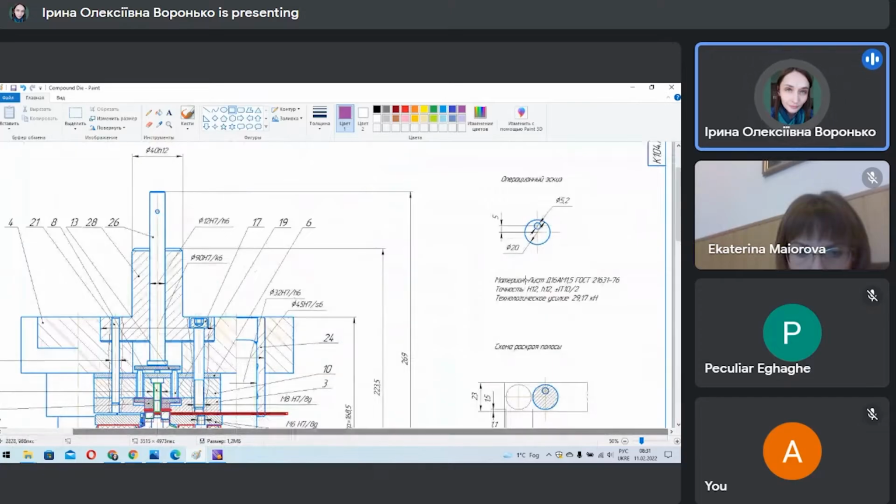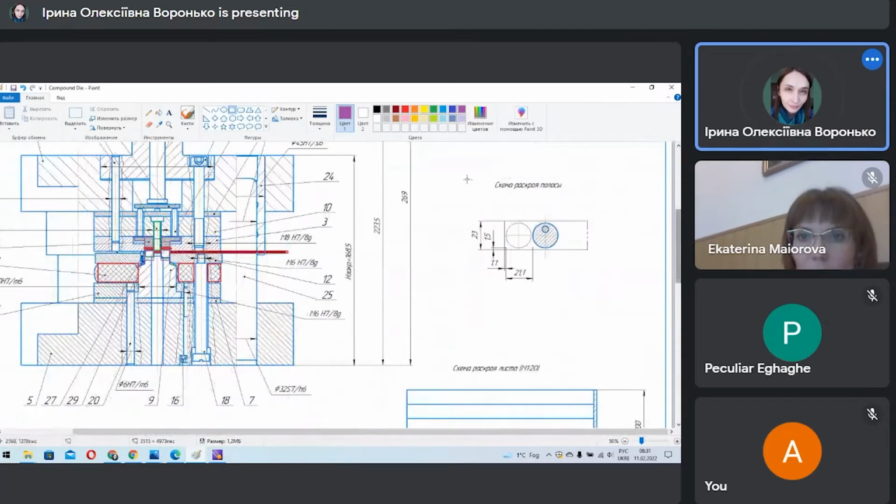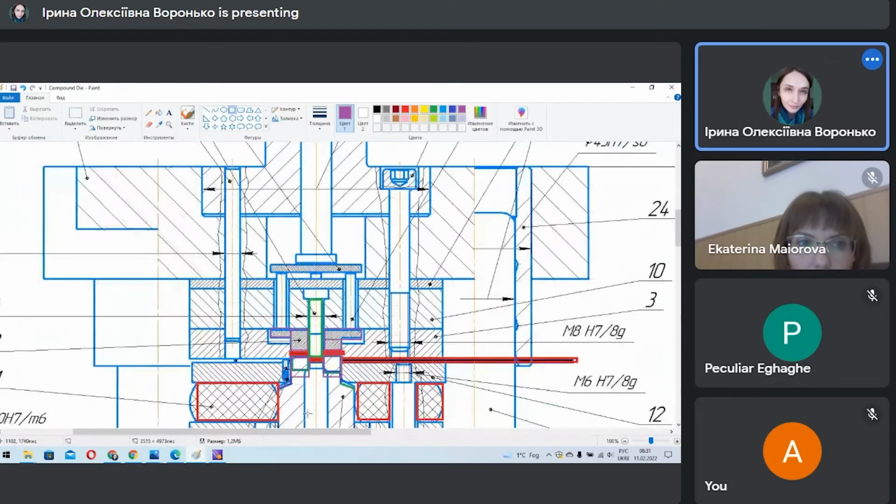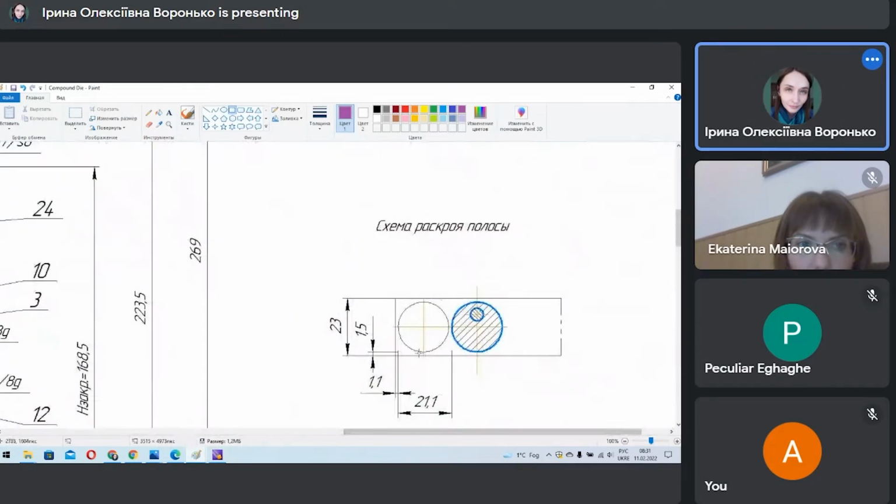So, you should decide how your part looks in this strip and find bridges between parts and between strips. Do you see? Between parts we have a bridge, and each time it will be equal, and a bridge will be between strips here.